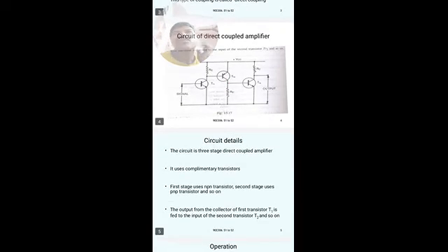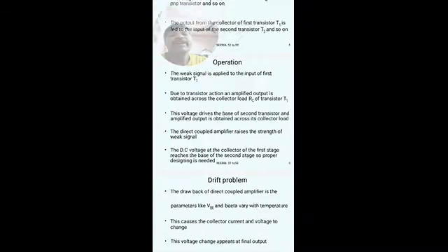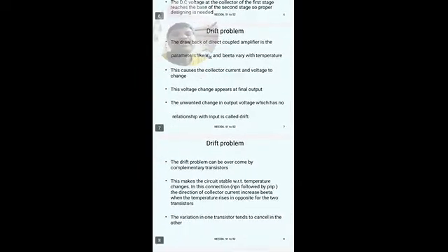So these two capacitances are going to act as a short circuit for high frequencies. Therefore the signal gets bypassed without the amplification by the transistor. So the gain rolls off at very high frequencies because of this electrode and wiring capacitance in the circuit.